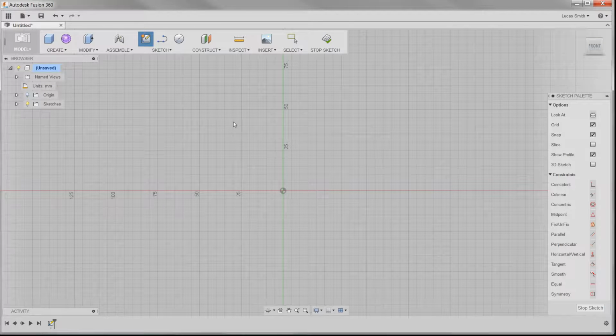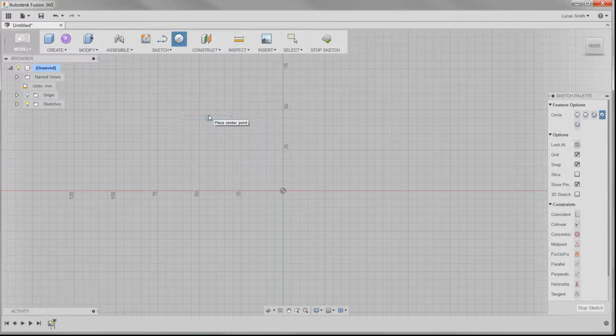If I wanted to use a gesture to enable a sketch tool, such as the Center Diameter Circle tool, I would go down and then diagonally up to the left. The gesture mimics this pattern. I'll hold down the right mouse button, then drag the cursor down and then diagonally up to the left. I'll press the Escape key to exit.